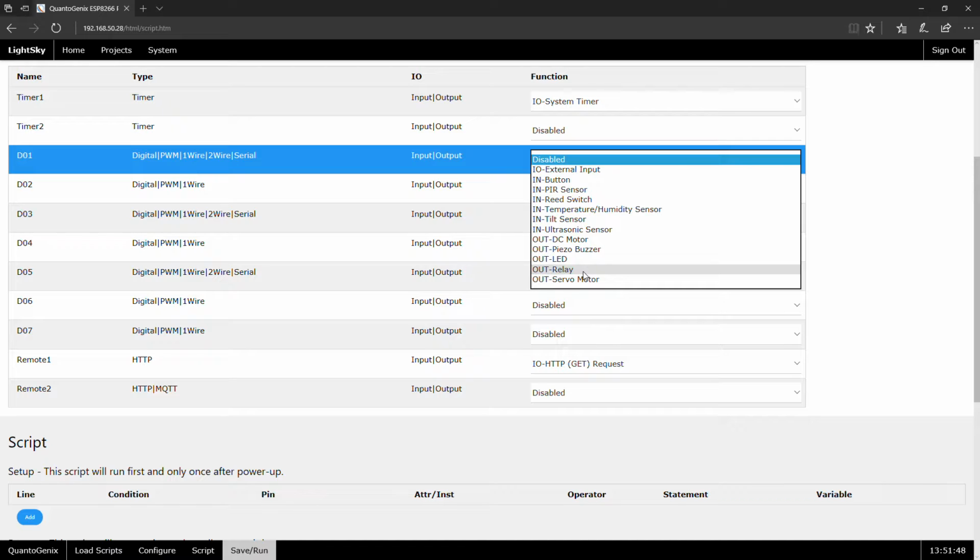Now the last one here is just a servo motor. A servo motor is unlike a DC motor. It's a very unique motor in the sense that it's not spinning like a normal motor. It rotates into a desired position. So we've configured the IDE to run from 0 to 180 degrees. So you can specify that the motor should be at 78 degrees, for example.